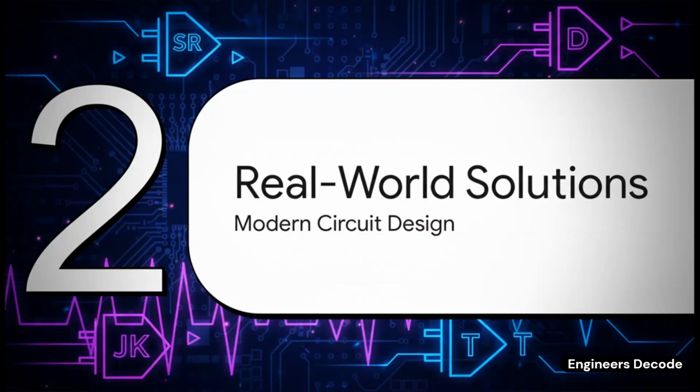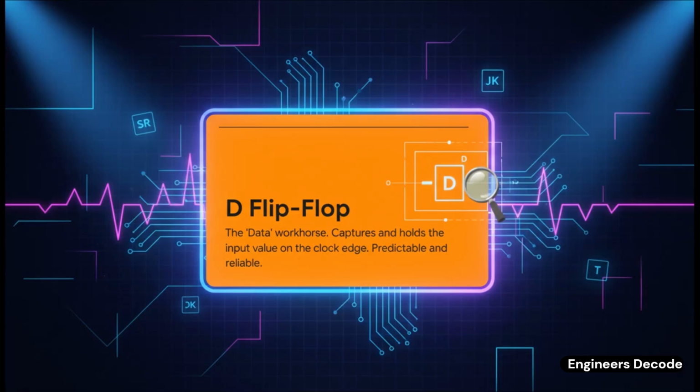These are the workhorses that engineers actually use today. First up, the D flip-flop. D just stands for data. It is the king of predictability. Whatever you put on the D input, that's what it captures and holds on the clock edge. Simple, reliable, no forbidden states, no mess. This is what you build things like shift registers out of.